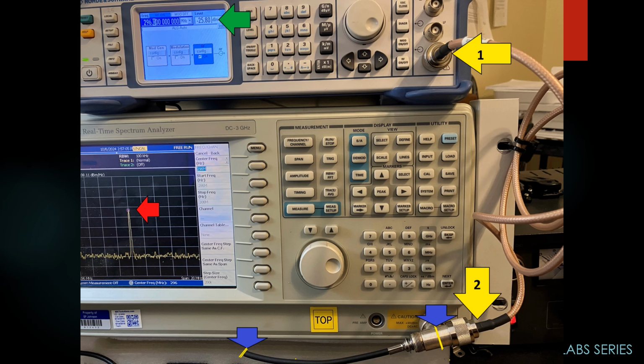So you kind of have to take into account the length of the connector, and I also took into account the length of the T from the middle to the end of the connector. So I used my tape measure and measured from the yellow line under the one blue arrow to the yellow line at the other blue arrow. That's my quarter wavelength.